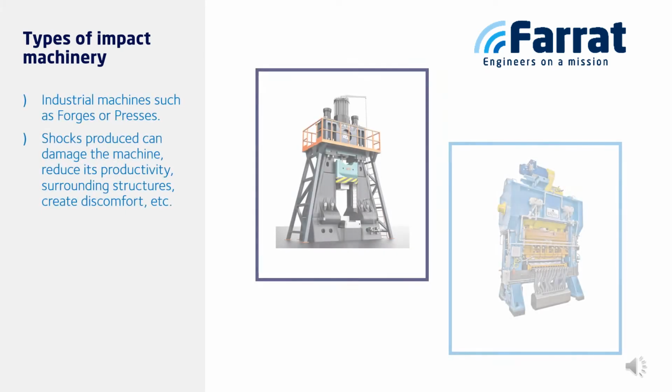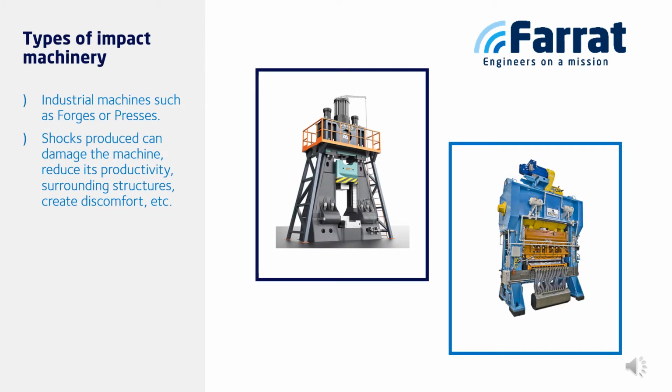External excitation acting on the structure can take many forms. The most common in the industrial world is the harmonic excitation that can be found when rotating movements take place. The second is shock, which occurs when percussion machines are used, such as impact machinery. Impact machinery generates impact. In mechanics, an impact is a high force or shock applied over a short period of time where two or more bodies collide.